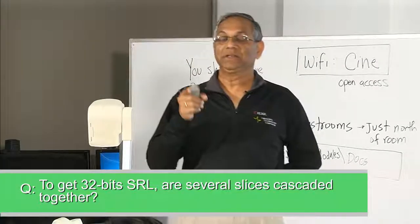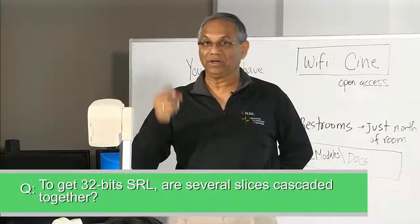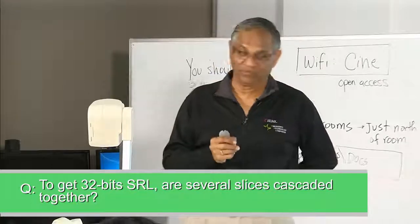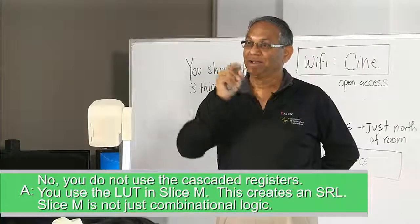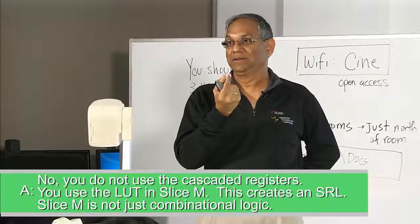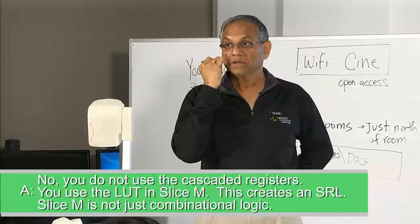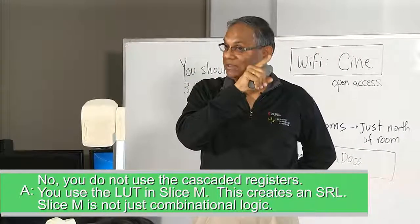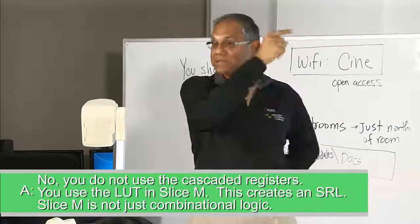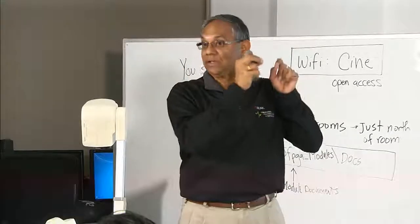Right. So, the question is, when you say 32 bits, are several slices being cascaded together, because in each slice you have only 8 flip flops? No, you do not use those flip flops. The lookup table is used as the SRL. But the lookup table is combinational. No, remember that slice M? Slice M has the lookup table that can be used as the SRL. So then you can't use that lookup table as a lookup table.